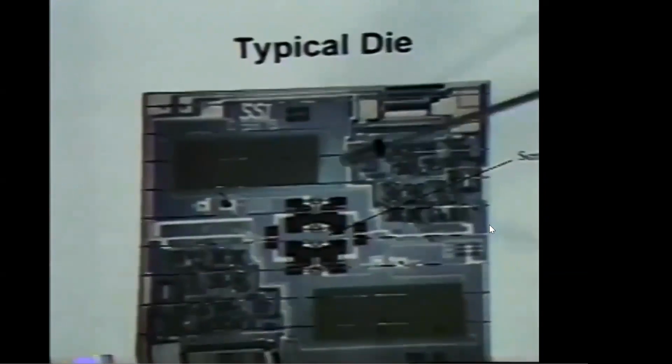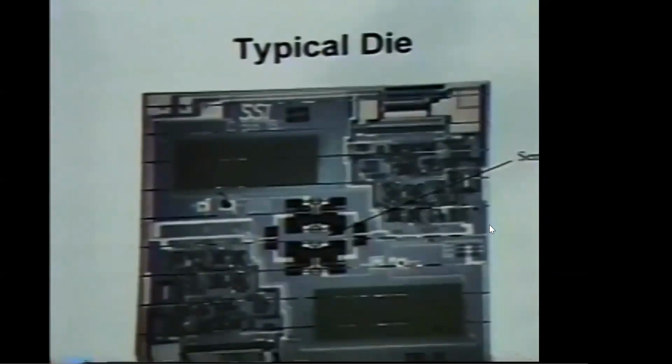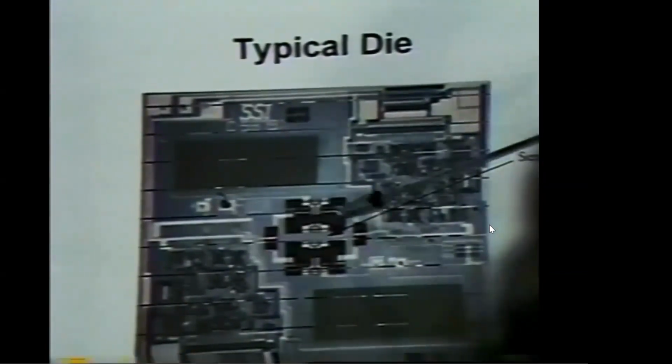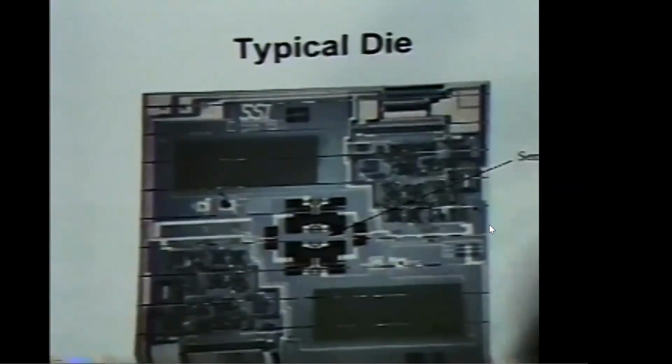So as I was saying, in the center of the die, you can find the 4 cavities that were created the way that I explained earlier. Beside those cavities, you find 2 banks of thin film resistors that we can use to trim the die, trim the membranes to balance them.